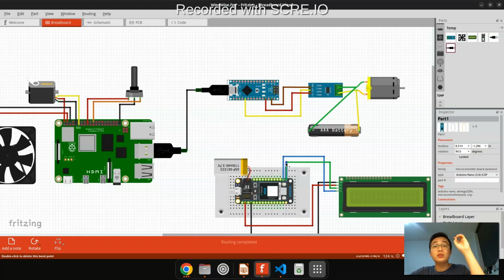Also, using a cable is better to transmit the data, because a cable is sturdier than normal jumper wires, and it can go as long as we need. Which means we can place the Raspberry Pi on the ground, or where it is approachable for us, and then the Arduino Nano is going to sit on top of the windmill, and they're all going to be connected with a serial cable, a USB cable.